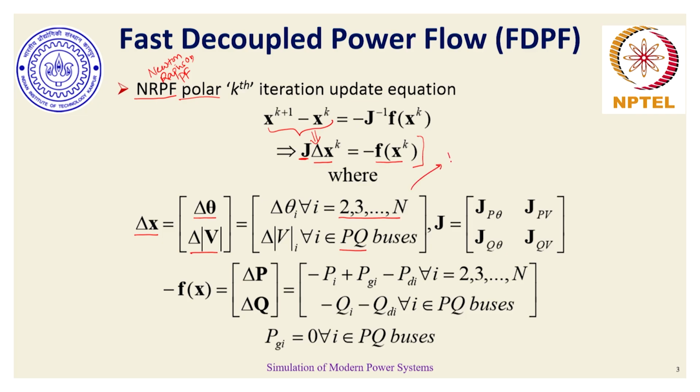Inherently, I am making the assumption here that for the given power network, bus 1 is the angle reference bus for which theta 1 is 0 radians or degrees, and V1, the magnitude, is specified as the value from active power loss minimization for the corresponding largest generator connected to bus 1.